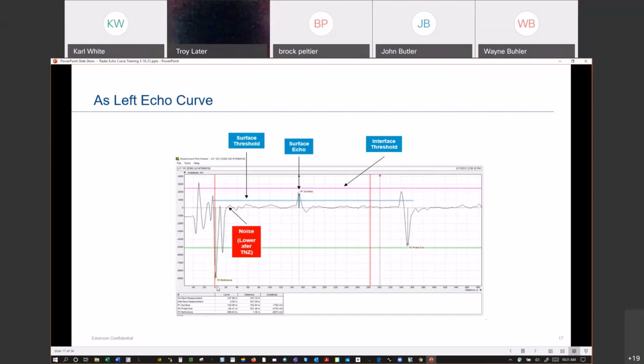And again, if you look at the amplitude, this one's kind of hard to read, but it's maybe negative 9,000. It should be a little bit stronger, but it's not because of this secondary peak. Going through that tall nozzle created this peak, and it took energy away from the reference pulse as well as the overall measurement. So anytime we can lessen those nozzle effects, you're going to have a much better reading.